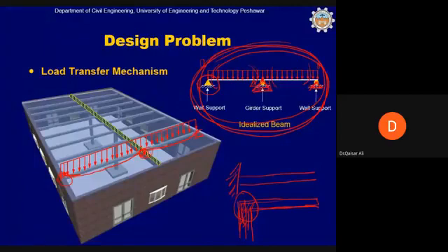Now coming to the last support. The last support is treated as roller support because if there is a thermal movement due to temperature increase, you know that the beam is having some flexure reinforcement, longitudinal bar. So this longitudinal reinforcement due to thermal movement will push these walls in the horizontal direction in this way, and there will be slight movement at both ends due to this thermal movement. And you know that hinge support cannot move.